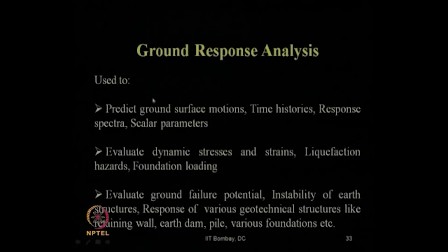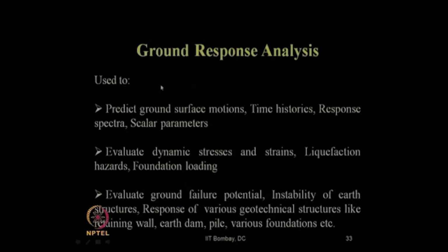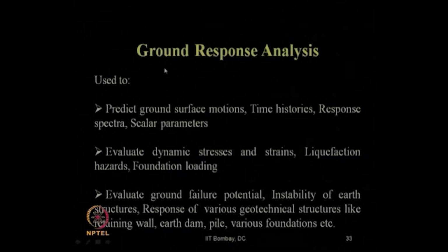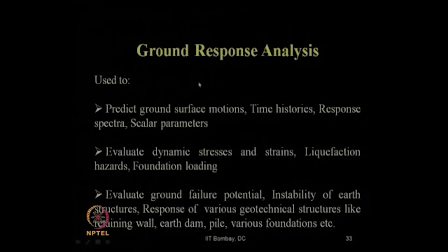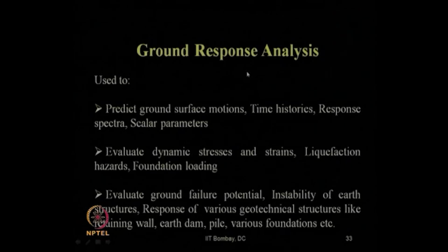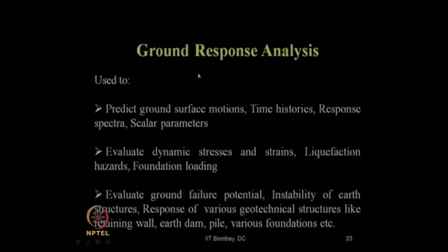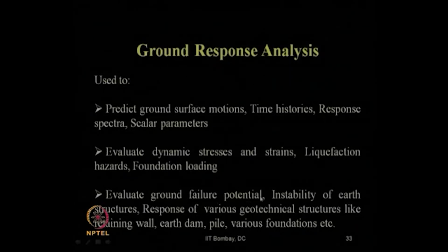How much extra lateral and vertical loading is coming from the seismicity of the event due to the effect of the local soil condition? That also comes from the analysis of ground response, which we will discuss in detail in one of our later modules. Then we evaluate the ground failure potential. For doing that also we require ground response analysis.